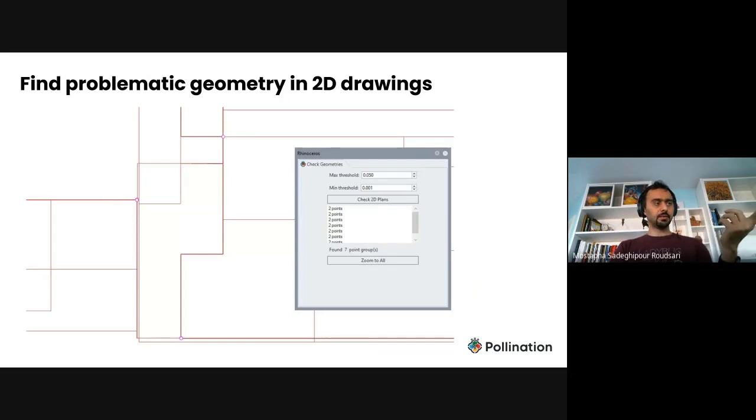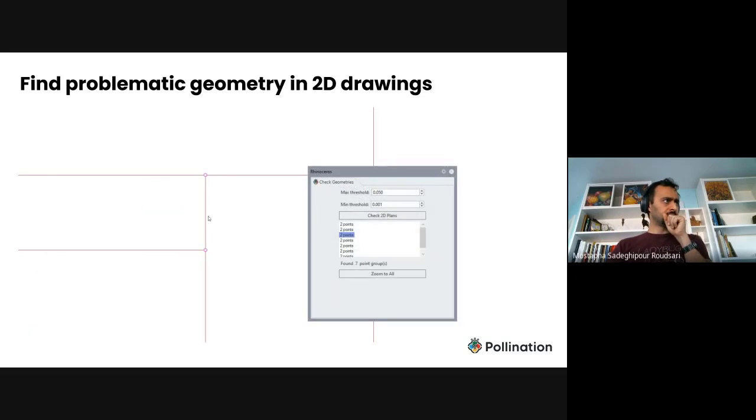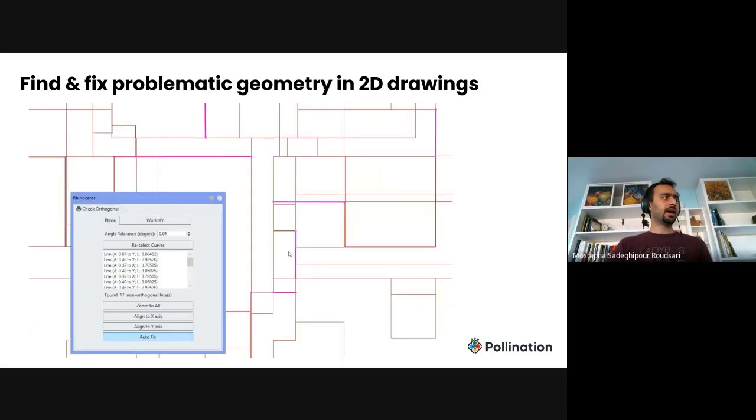We have the same functionalities in 2D. We have seen a lot of people do this work of bringing the model in, drawing all on the line, and then end up with this. And you don't notice until you extrude your geometries and do an intersection, and you end up with cases where they're very close that you don't even see. Now you can see cases like this and identify those quickly, and we have a command to even fix it automatically for that one.